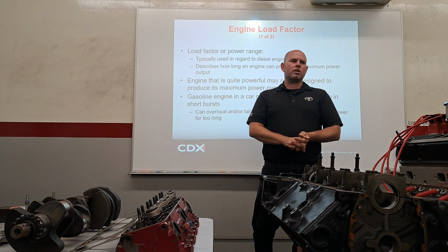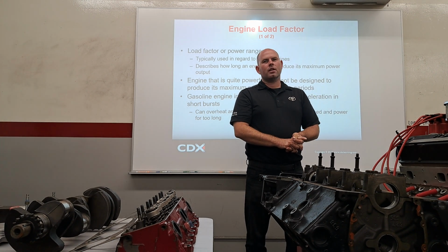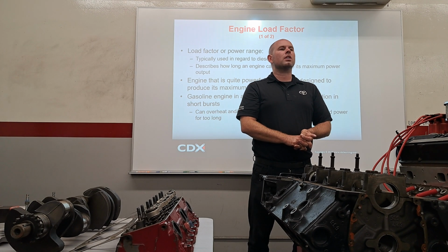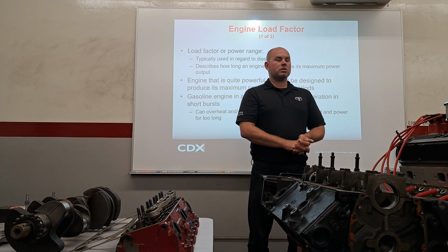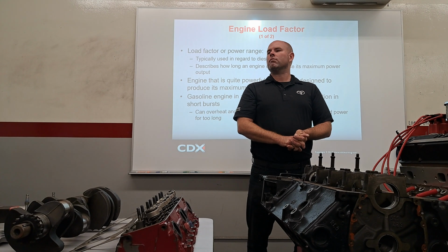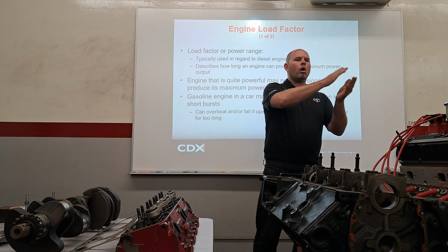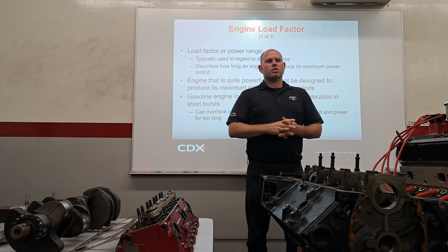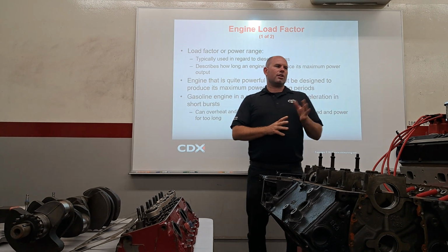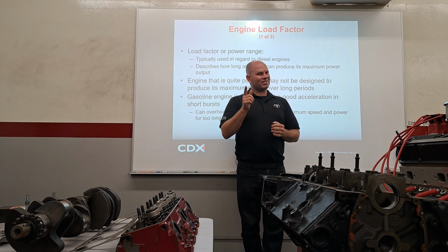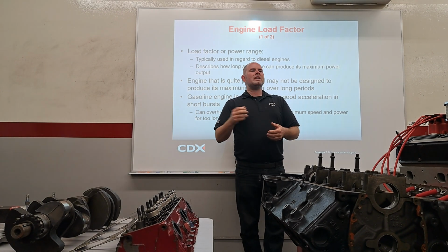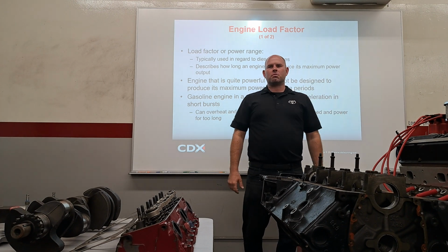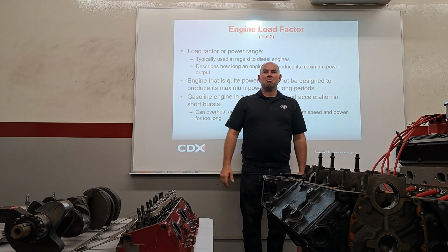Apply that to an electric motor. Electric motors like 0 RPMs, I'll give you everything I got as soon as I start moving. 10,000 RPMs, I'll still give you everything I got. They will make all the power and all the torque at any range. So if you look at an engine and all those sweet memories and sounds, which I appreciate, I do, we need to put a transmission on the sucker to keep it in its power band, and electric motors like transmission, don't need it, never had one before.